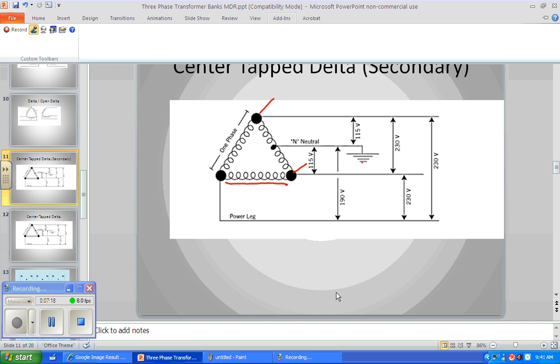And what does that do? That means one of the transformers is going to have to be larger than the others because the load in the three-phase is going to be completely balanced around the load, right? Each of the phases, that three-phase load is going to be balanced. But this single-phase load is going to be out of balance. So we're going to have one transformer that's larger. If we can figure out which single transformer is carrying that larger load, we want to use a bigger one where that one is, right?